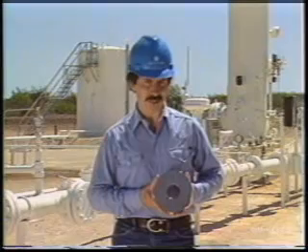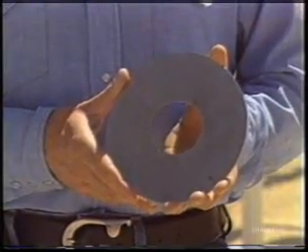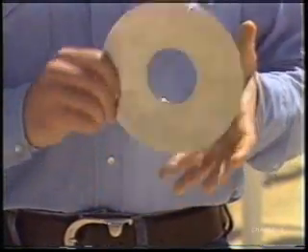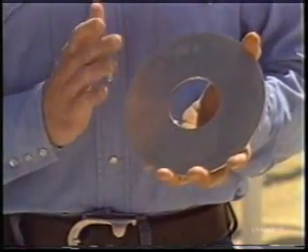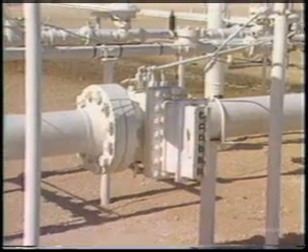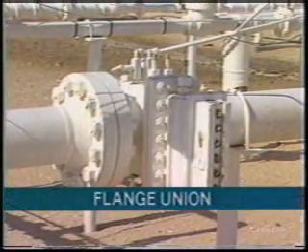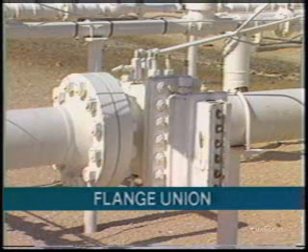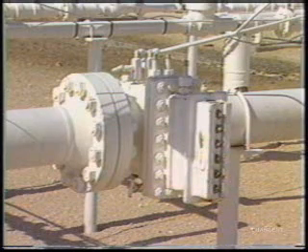An orifice plate like this one is designed to create a pressure drop in the meter tube. It is a flat steel plate with a circular, square-edged hole carefully machined through it. The downstream side of the orifice plate is beveled and must be properly set in the orifice fitting or flange union. The orifice plate is held in position in the meter tube by flange unions or orifice fittings. There are several types of orifice fittings, such as the senior, junior, and simplex. Check with your supervisor regarding what unit is used in your area.